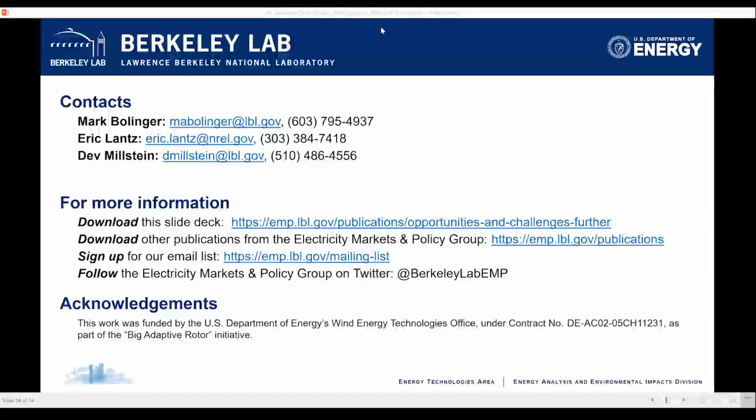Yeah, so thanks, Devin. I guess I would just add to that: if you take that one step further and look at the value impacts, it's also important what the wholesale prices are doing in any of those given hours. The value boost really comes from a greater proportion of the wind generation occurring during low wind speed hours when, at least in some markets, wholesale prices tend to be higher because there's less wind in general or in total flowing onto the system.